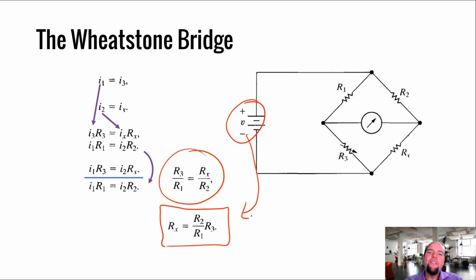So it doesn't matter. Even if this voltage supply was 10.25 volts, even if this voltage supply was 10.279 volts and it was wiggling a whole bunch up and down, if we follow this process using a Wheatstone bridge, we can still accurately find resistance with whatever accuracy we can control the resistance of a tunable resistor. It's very powerful. This idea that we are essentially finding an unknown resistance in a way that rejects the voltage that's used to make the currents and voltages be produced in our circuit. It's very, very, very, very powerful.